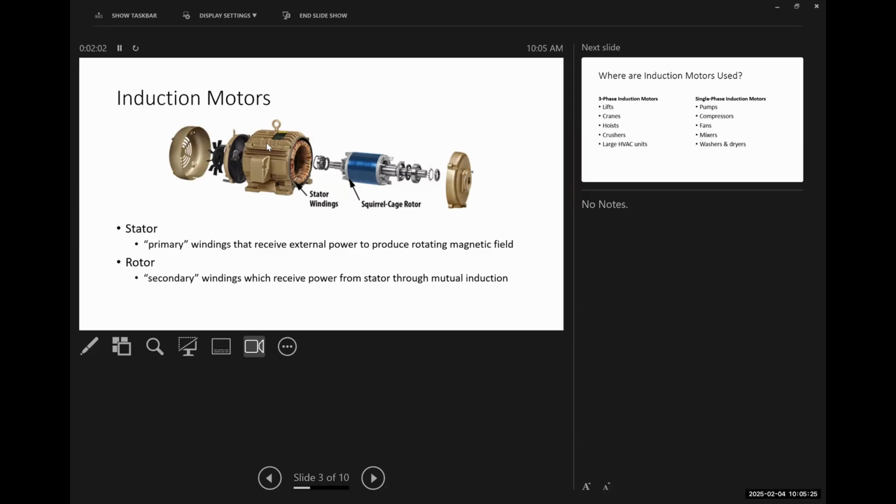And then we have our rotor, which is located inside the stator windings. It is a cylindrical machine overall, so effectively the rotor fits inside of the stator so that there is a constant amount of air gap between the rotor and the stator, so that we don't see any change in reluctance due to changes in the air gap overall.